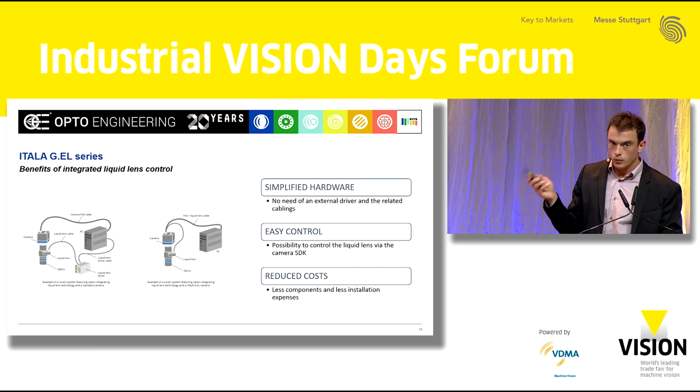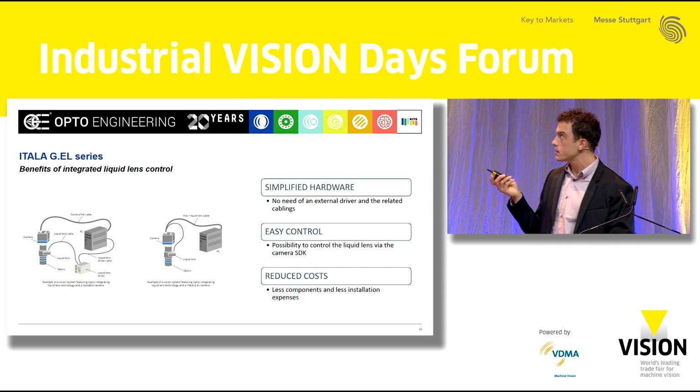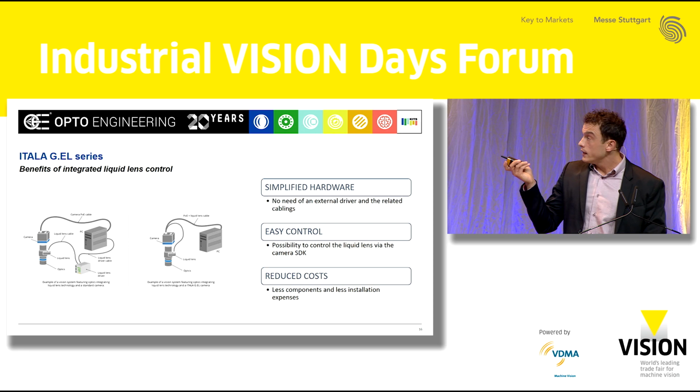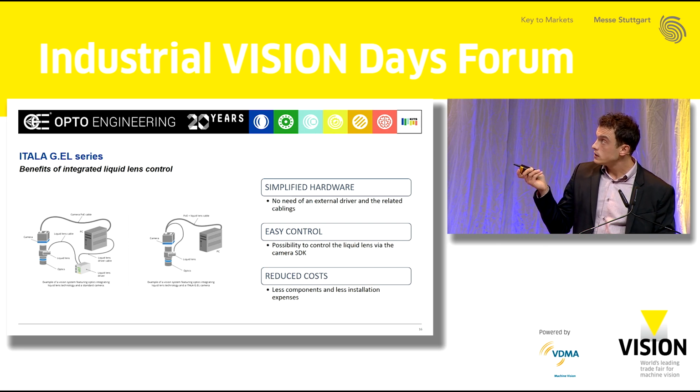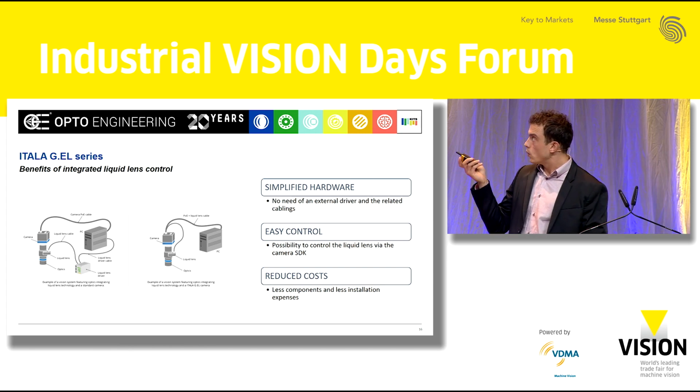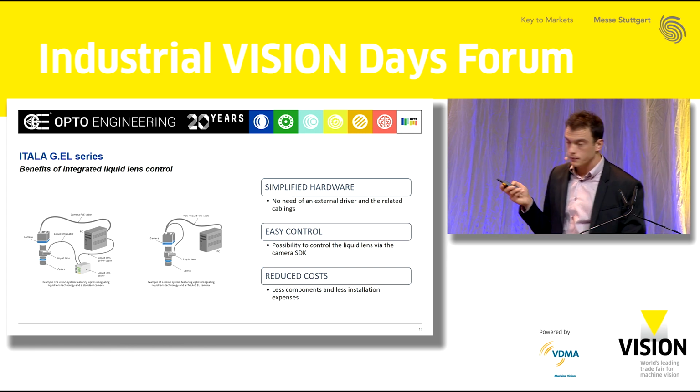If you're not, there is also a second cable from the camera to the PC. Then the liquid lens needs to be connected to the driver with another cable, and then a third cable from the driver to the PC. Of course, this is quite a complex system.